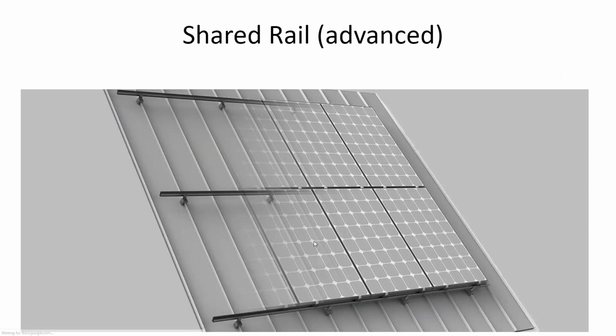Let me give you an example we just looked at. This is funny. I know that they probably regret this photo because there's a problem with racks going on a standing seam metal rooftop, which is that the standing seam panel gets clipped to the roof deck as it's being put on and built across the roof. So each one of these metal, 16-inch wide channels is clipped. But the spacing for these attachments is now skipping across channels. And so this standing seam metal rooftop, the solar array is attaching to the metal panel.